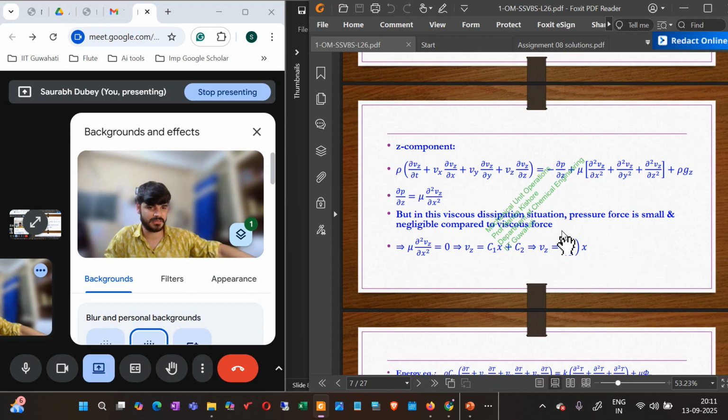So here you will get linear velocity. Even if you are not given that the linear velocity profile is there, you can calculate it using our conservation equations, right? So is that clear? So what is important right now? You are looking at various derivations, some model problems, and you are using the standard equation of motion in Cartesian and cylindrical coordinates along with the equation of temperature distribution, whatever you have derived for the non-isothermal cases, right?